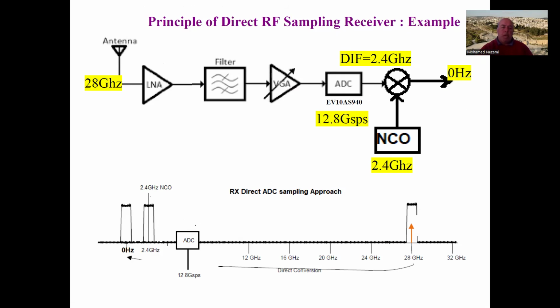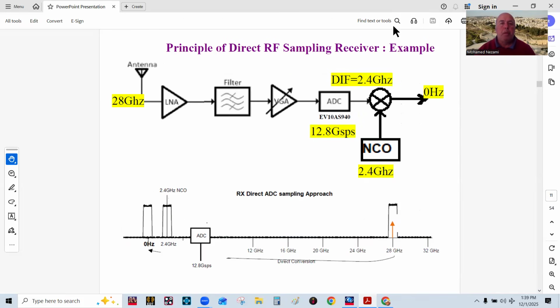So the first thing we hit this signal with is we decimate these samples. We could decimate, for instance, by 10, 100, or so on. Well, it has to be multiples of 2 to the n. And so you end up with an appropriate rate that you can feed into the demodulator and be able to do that.